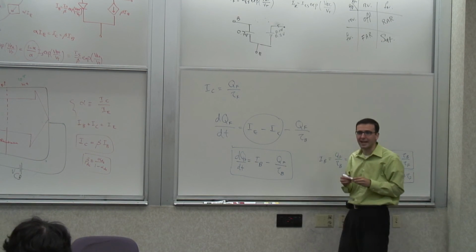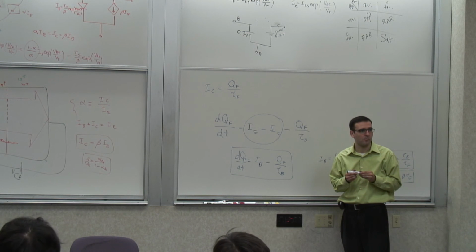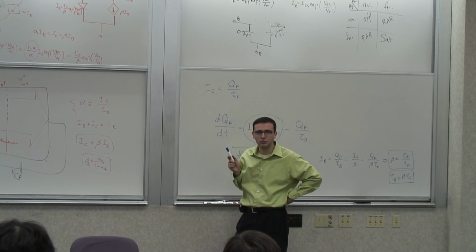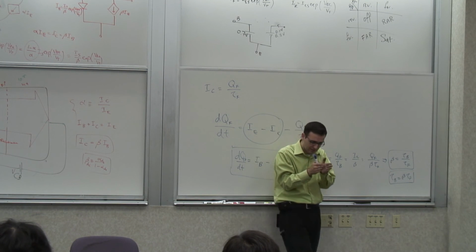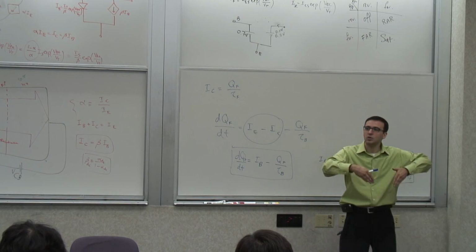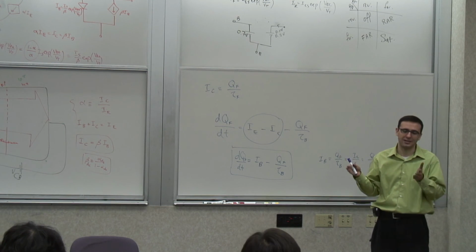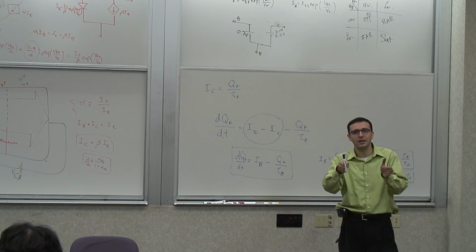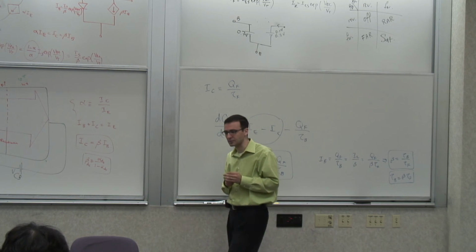Now, that's one of the things that affect the dynamics of the transistor. What else affects the dynamics of the transistor? Right, we've got two junctions there: the base-emitter and the base-collector junctions. Each one of them has a capacitance. We saw that, right? We calculated the junction capacitance. So these capacitors need to be charged and discharged when you change the voltages. You need to provide some additional charge, so you have some time constants associated with that, which will slow you down. Later on, when we do the dynamics of the transistor, in EE114B, the next part of the course, we'll calculate the response of the circuit based on these individual time constants, and for that we need to calculate these individual capacitors.